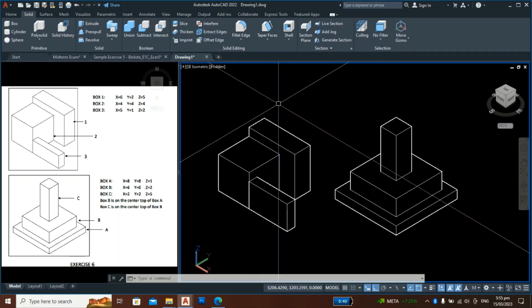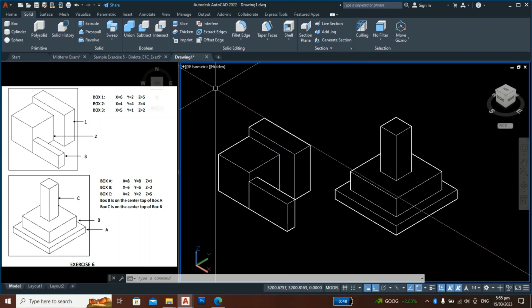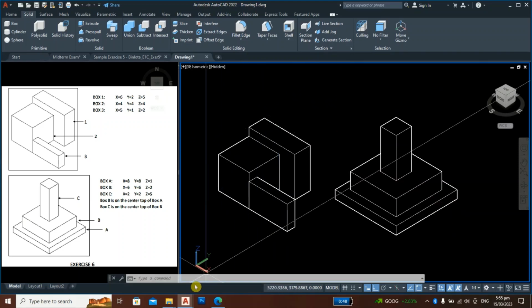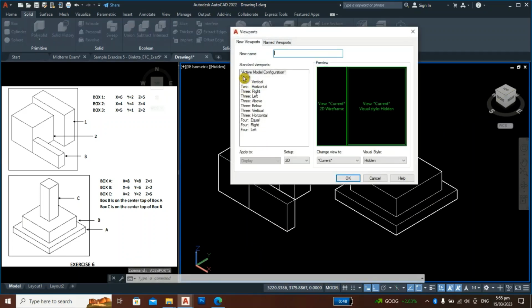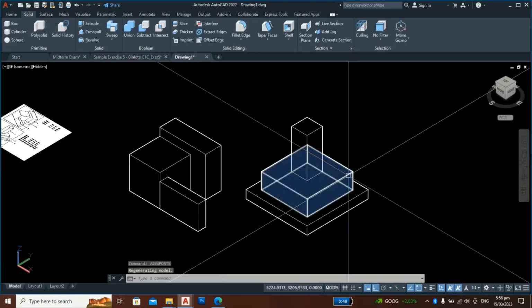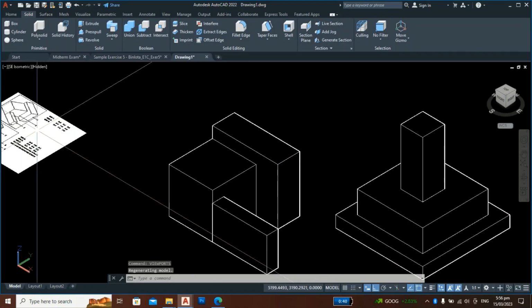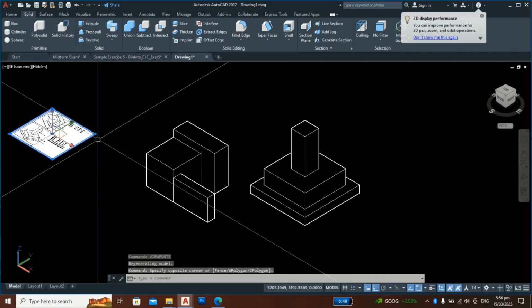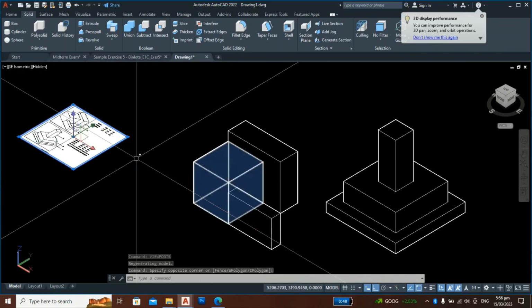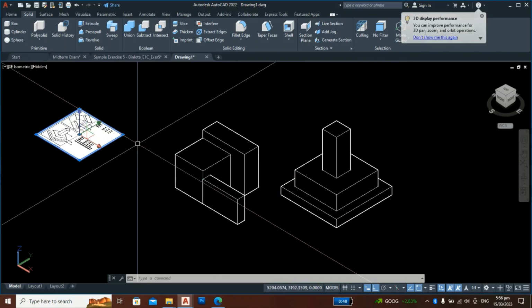and you are ready to compose your final drawing. So go back again here, or type, okay, type viewports, okay, then select single, then click OK. Now either you want to erase this image which you made as reference for the dimensions to draw this drawing, okay, or you can keep.